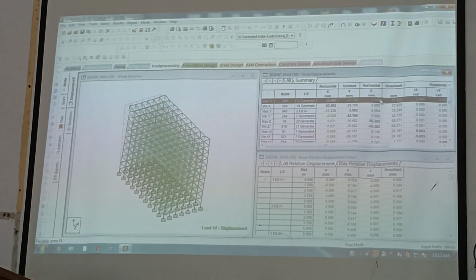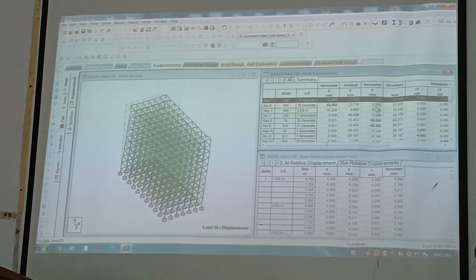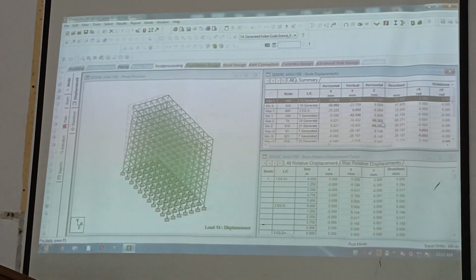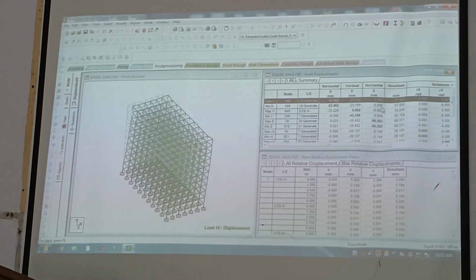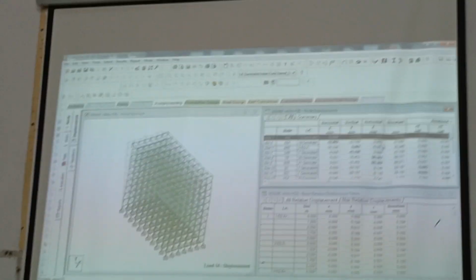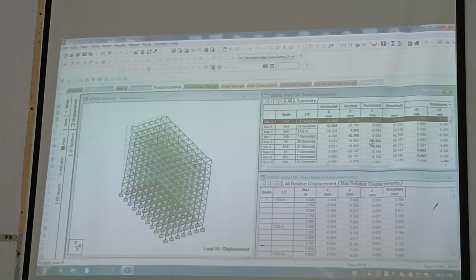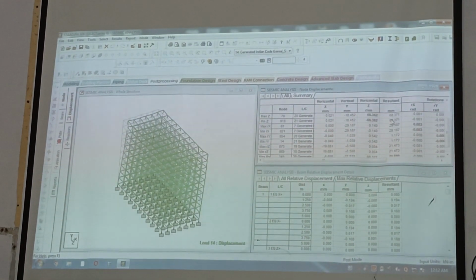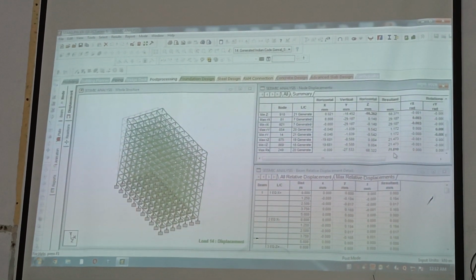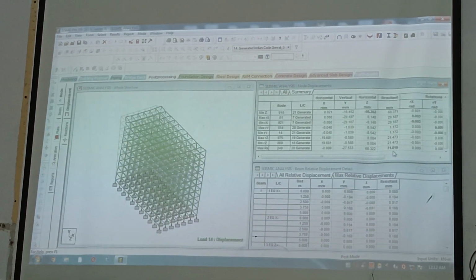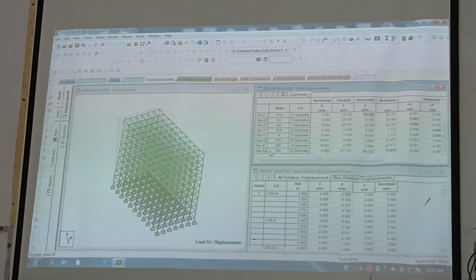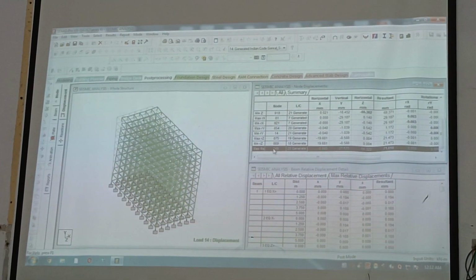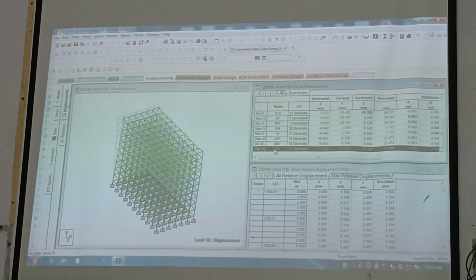Summary of displacements. How much summary you will get for displacement values in all directions. These are the critical load cases for different critical load combinations. Parameters to study. What is the maximum displacement? Can you see that in certain columns? Which is the highest value? 71.01, sorry, it is at joint number 240, compared to all the joints and load cases.